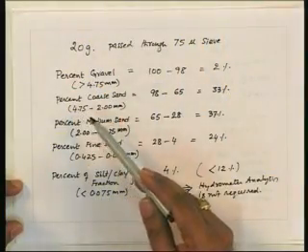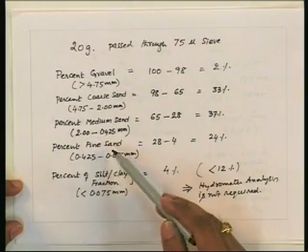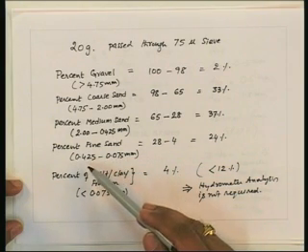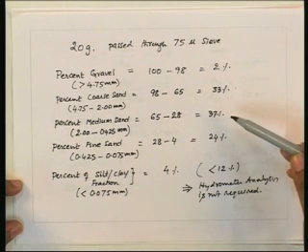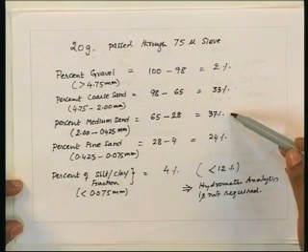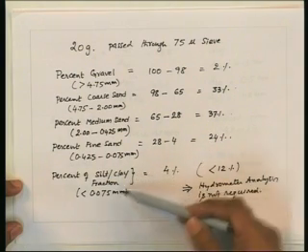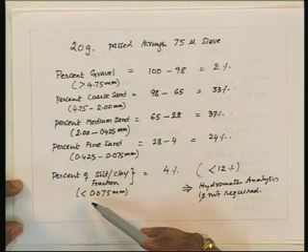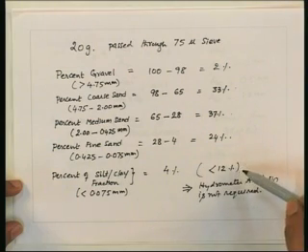Similarly, percentage coarse sand ranging from 2 mm to 4.75 mm, percentage medium sand 0.425 to 2 mm, percentage fine sand ranging from 0.075 mm to 0.425 mm, which gives us percentage coarse sand as 33%, medium sand as 37% and fine sand as 24%. The percentage silt clay fraction, particles having sizes less than 0.075 mm, is 4%, which is less than 12%.